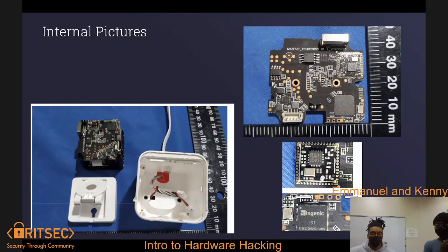Also, back to the obfuscation stuff. This is a requirement by the FCC for all devices that use radio frequency, right? But like I was saying before, they're not required to actually label the chips that are on the devices. So in situations like a crypto wallet, you don't want your competitors knowing what chip you use to implement security, so they'll just wipe the chip entirely. That goes back to reversing and taking X-rays of the PCBs to determine what it is actually doing. So this is helpful in our case. However, in the future, it won't be.